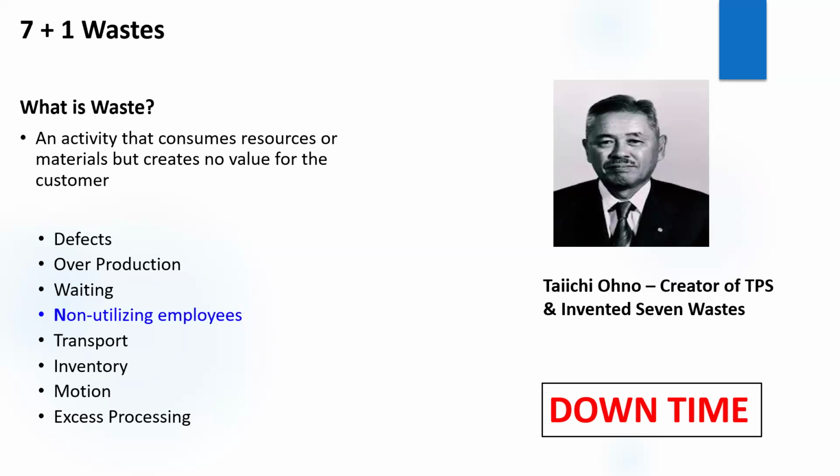defects are called waste, because as per definition, waste means an activity which consumes resources but the customer is not willing to pay. And for those 20 pens, we have used the resources. Manpower is used, raw material is used, energy is used, electricity is used, compressed air is used, but the customer will not pay for that, and hence defect is treated as waste because the customer will not pay for a defective product.